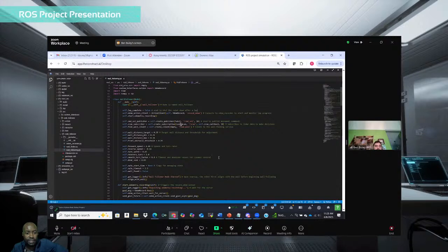The trajectory. So are you saying that during the course of the dead zone, it's not supposed to be making any either right or left turn maneuvers? Yes, that's exactly right. I had to incorporate it early on because I found that if not, it would be going along the right wall, and even if it's fairly close to it, it would begin turn-left behavior, and it would make it very jagged.